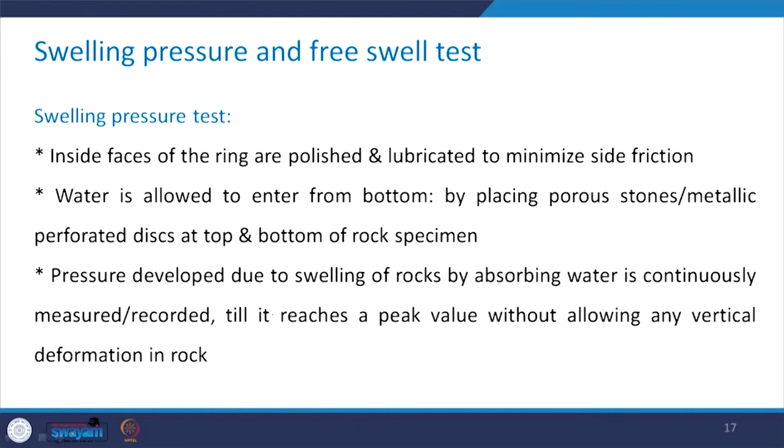Then what will happen? The moment the water goes inside the rock specimen, it will start swelling, it will start increasing its volume, and I am not allowing it to deform because of the constraint. So, the pressure is developed by the rock absorbing the water, and that is continuously measured till it reaches a peak value, without allowing any vertical deformation in the rock.